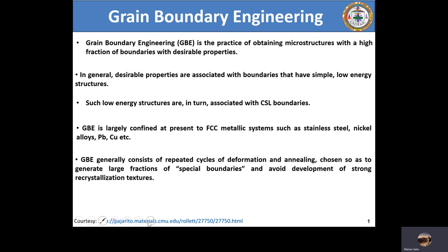There, the overall boundary energy in a given section of the microstructure is very, very high, and as a result, when we etch it, there's a huge chance of over etching, which we definitely do not want, because in that case we'll end up having corrosion products deposited at grain boundaries. Although we are able to look at the grains, we don't want such boundaries to be decorated with corrosion debris or corrosion products.